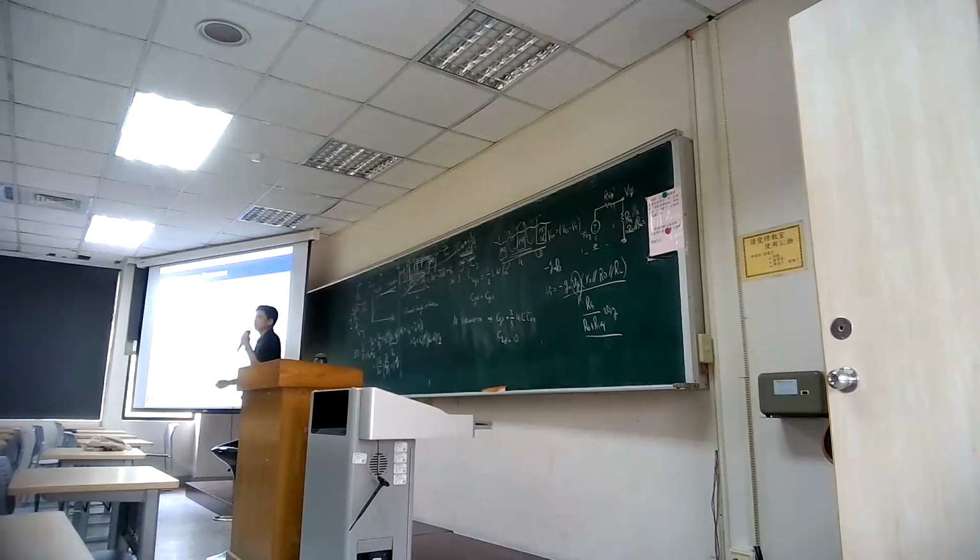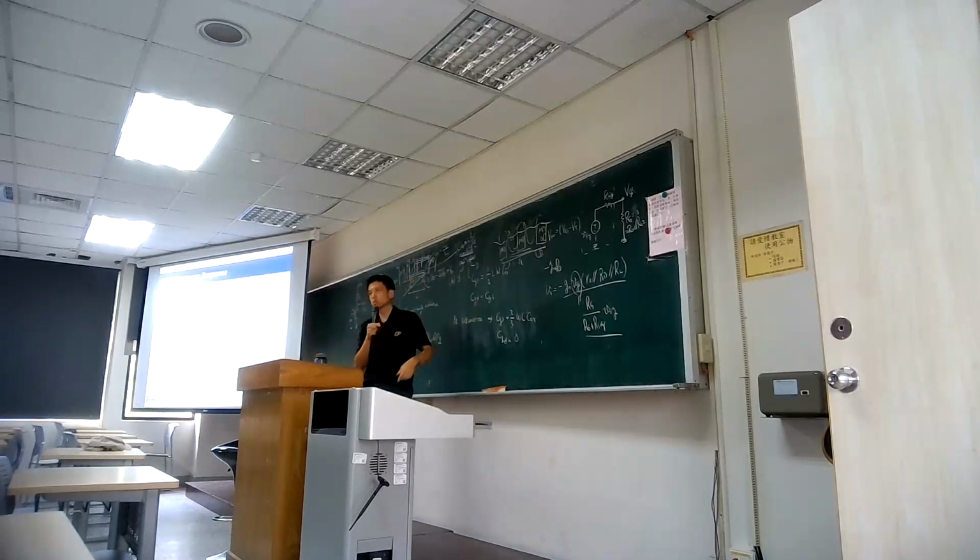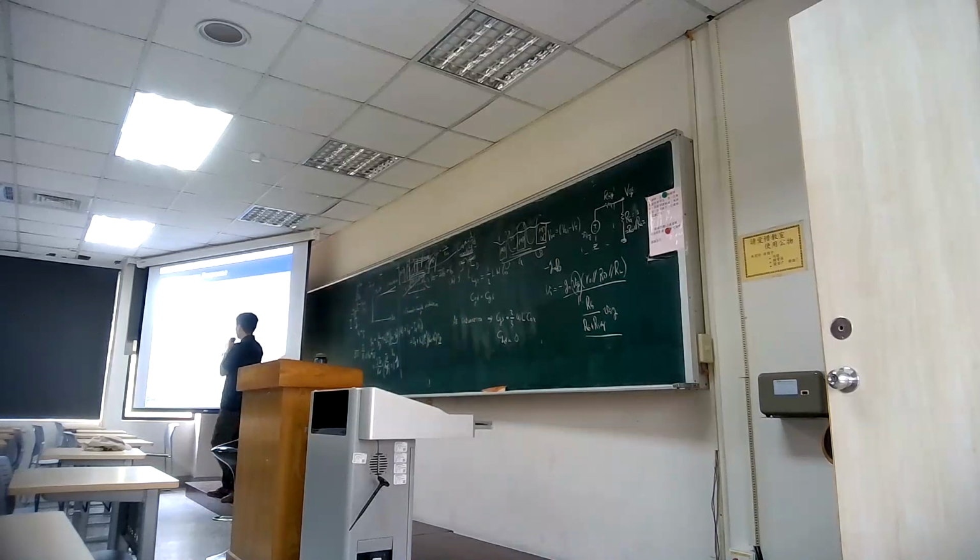Maybe you can say CGD is not so important because the voltage may not be significant, but you still need to consider it. I will talk about why. In the triode region, we get the same charge distribution, so CGD equals CGS.